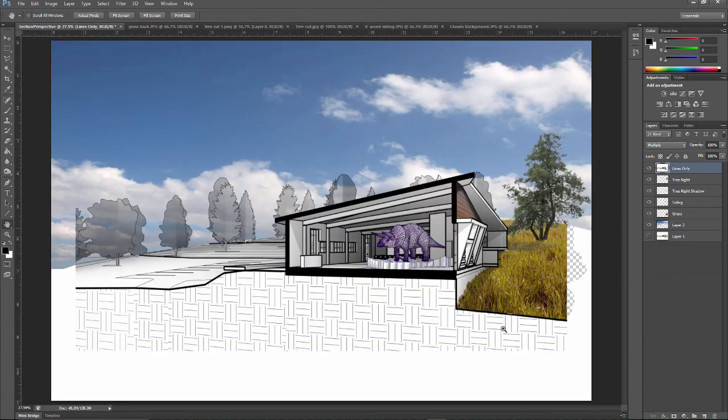So let's double click that and move that out, and you can start to see, if you're looking at this edge, how to put together a really quick, concise, nice looking rendering using the section perspective tool in Revit and a few of the key tools in terms of building a composition with Photoshop, matching some photographs together, getting some key elements built in place to build a very quick but also a really nice image that hopefully pays attention to color palettes, that starts to build the image of what you're wanting the building to do without going through all of the steps to build all the materials and seam all the materials inside of a 3D program like Revit to make sure that the renderings are perfect.